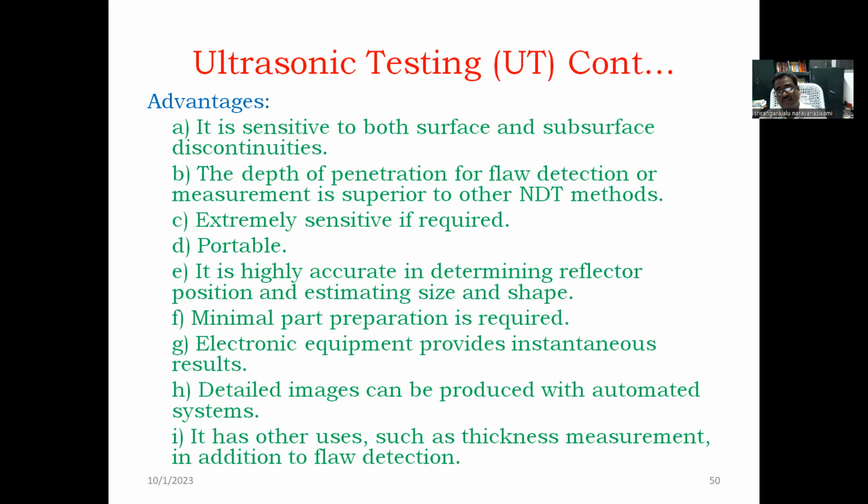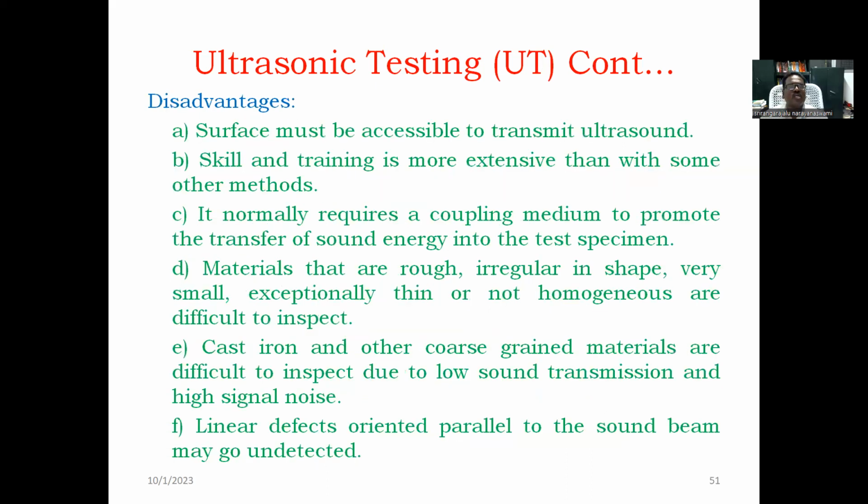Flaw detection is also possible. So disadvantages: the surface must be accessible to transmit ultrasound. Skill and training are more extensive than with some other methods. It normally requires a coupling medium to promote the transfer of sound energy into the test specimen.